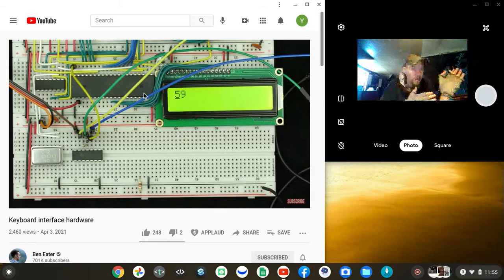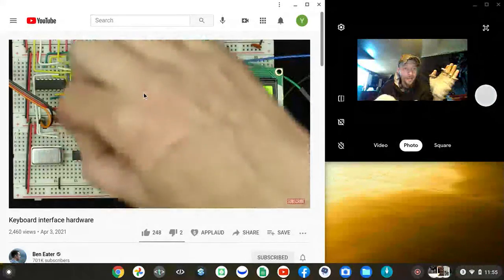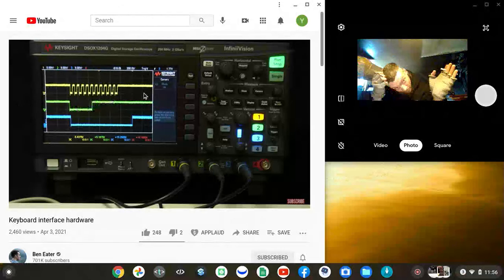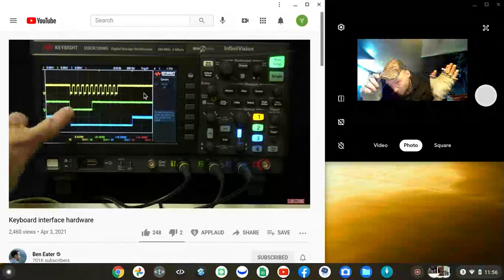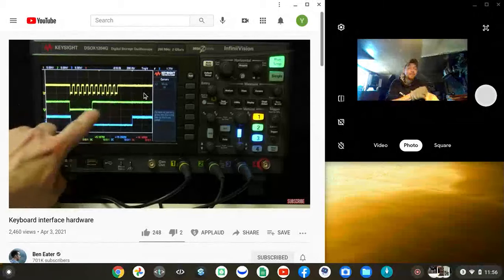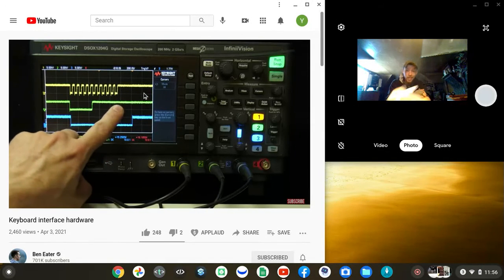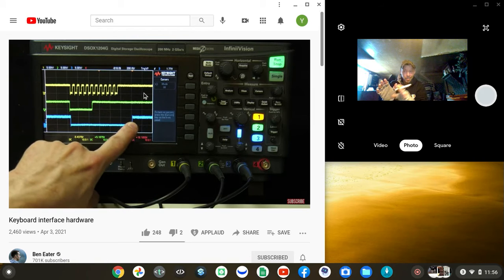Because the nice thing about this setup here, if we go back and look at the data pin here, we're reading all of the bits. So we can feed all of this into the shift register, and then use this rising edge to trigger an interrupt.